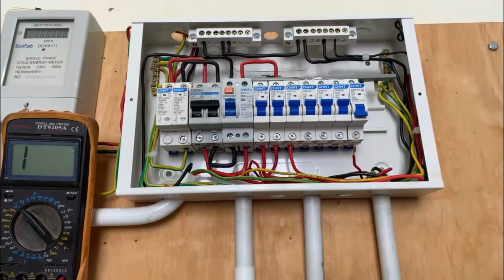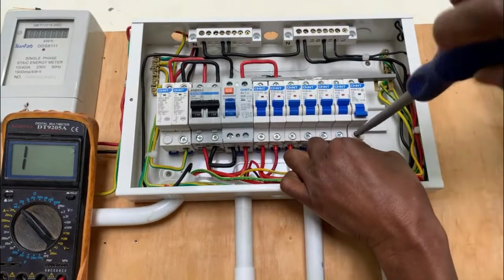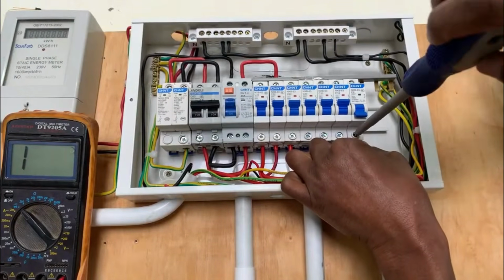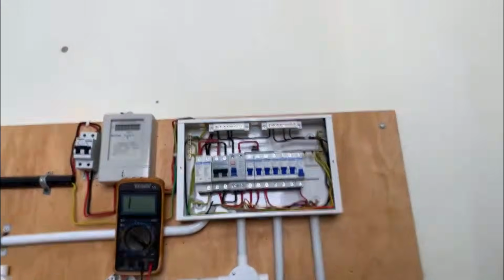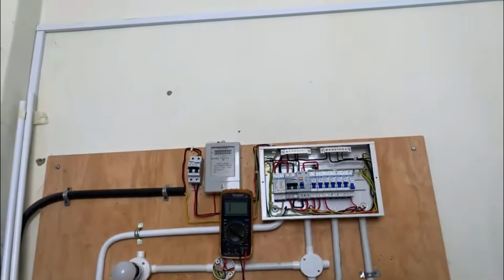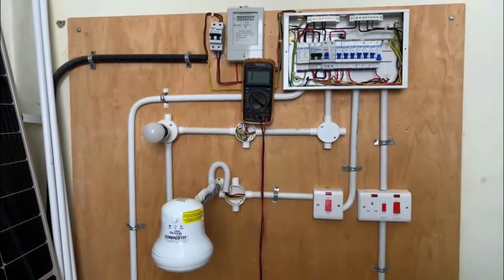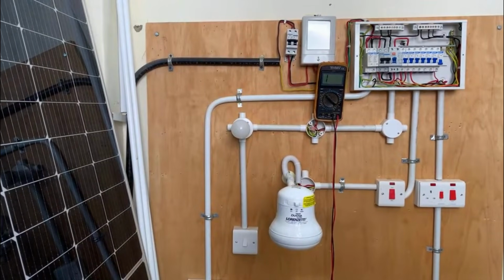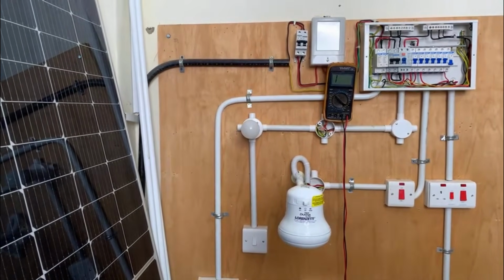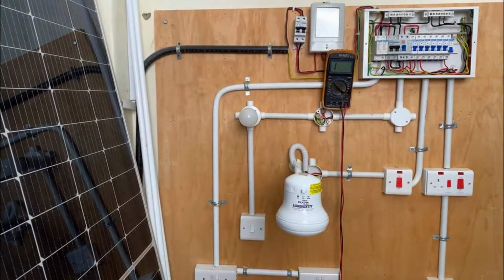So now we need to connect back the cable. Very simple for us, we connect it and we screw. This will be the first time that we'll be putting the line on, or the MCB on, since we have rectified the problem. We used our digital multimeter to test for continuity. We confirmed that there was continuity, and so we are going to switch it back on and test for the presence of electricity in that circuit.